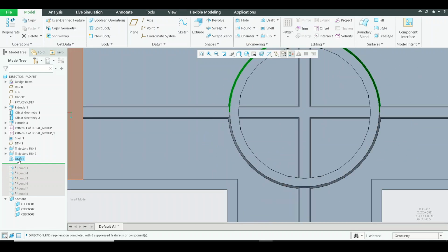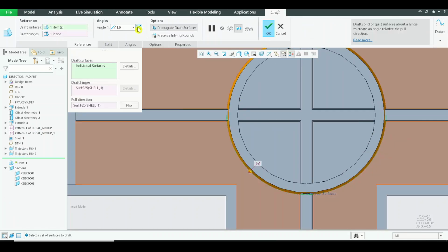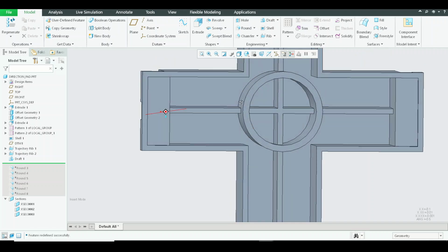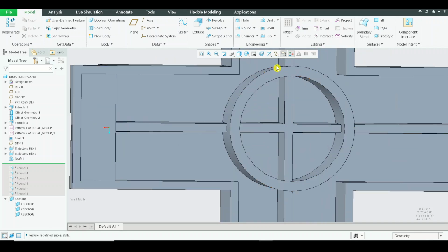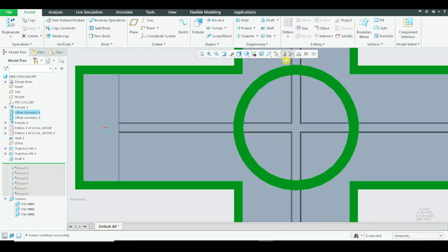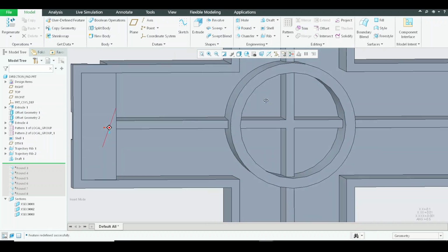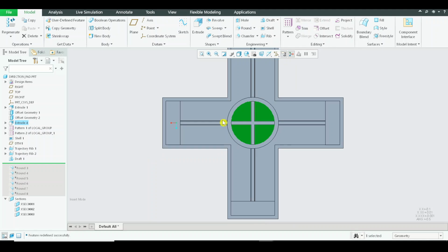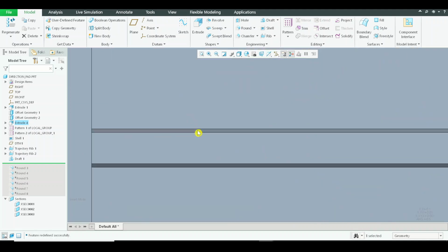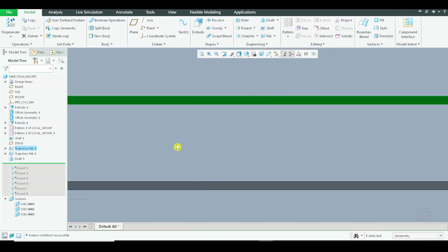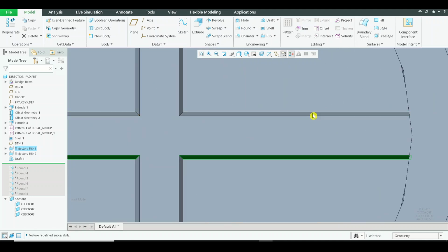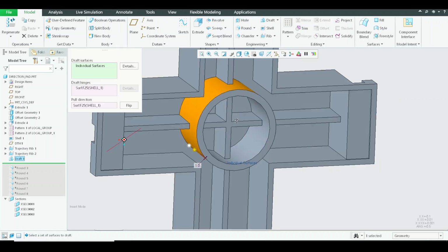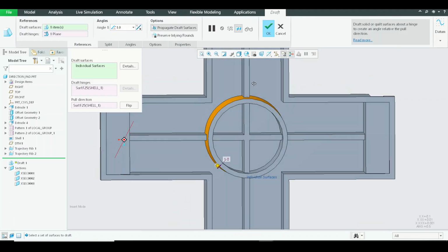Okay, but if it is on the other side, you cannot see the inside wall. That means it is an undercut. Okay, and undercuts should not be present for these parts actually. Okay, this is an undercut. So the trick is to ensure that when you're aligning the part to the direction in which it is pulled, you must be able to see these walls, because the ribs are already drafted. You can see these walls, so this can be easily pulled out. That is the trick.